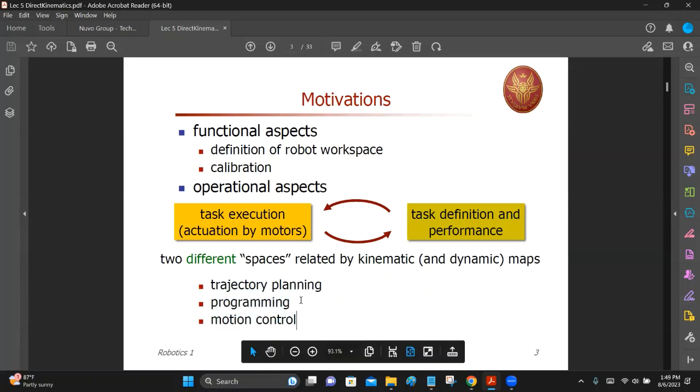So there also you saw a video I showed you 2 weeks back probably, how you program a robot manipulator. What is the first point, second point, third, and so on. Then the robot understands these via points, and then it interpolates between points, so many points in between, right?